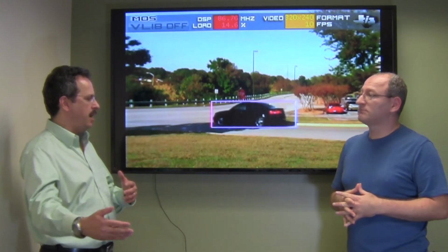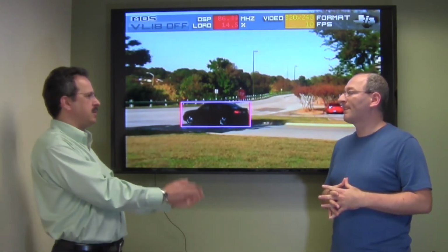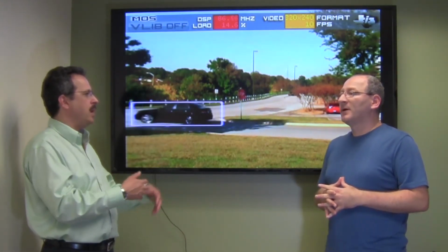So this is a library of vision functions that TI has optimized for the DSP. Correct. But it also provides non-optimized PC versions for prototyping purposes. Exactly. I guess the advantage of using that library versus something like OpenCV would be that in the OpenCV case, the optimized implementation doesn't exist for the DSP, so I'd have to do that myself. That could be one of the reasons.